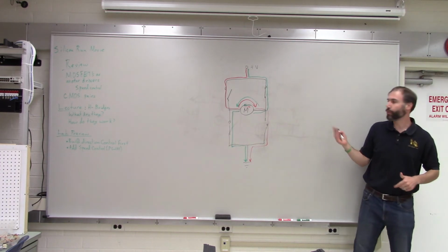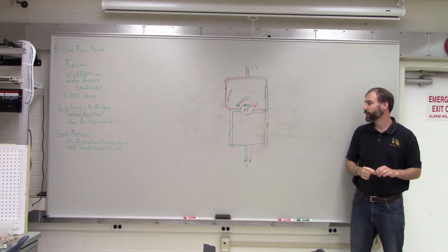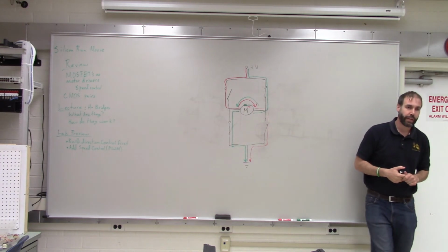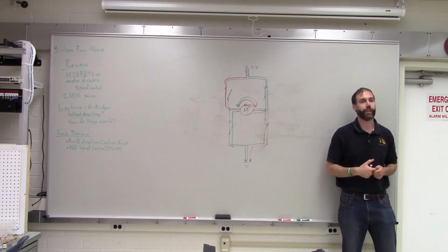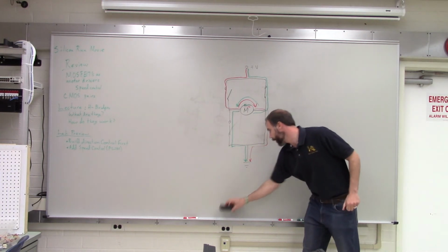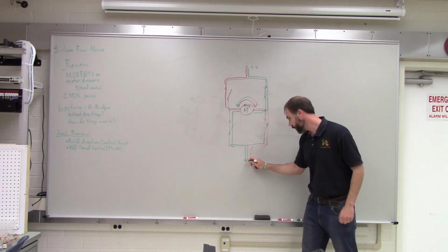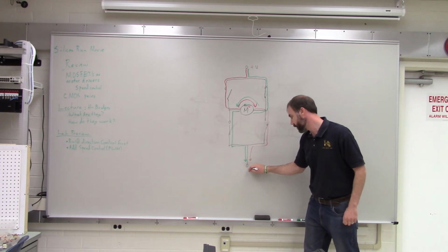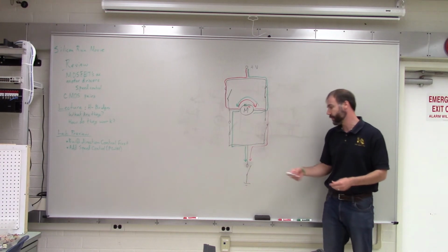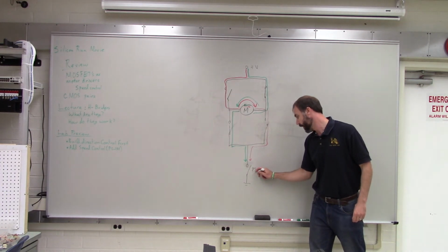Okay, so that's how we control the direction that the motor is turning, but I still haven't said how we control the speed, right? Well, last time we used PWM to control the speed. So we're going to use that trick again, okay? But this time we're going to put an extra switch down here at the bottom. Again, I'm saying switch, but it's actually another transistor. So we're putting an extra transistor down there, and we control this transistor with PWM.